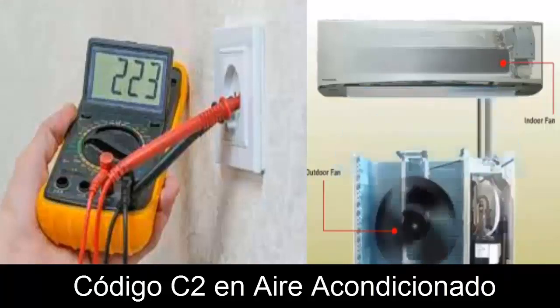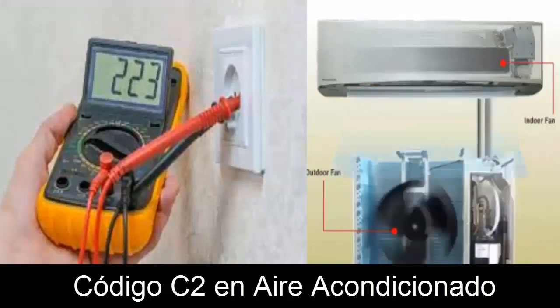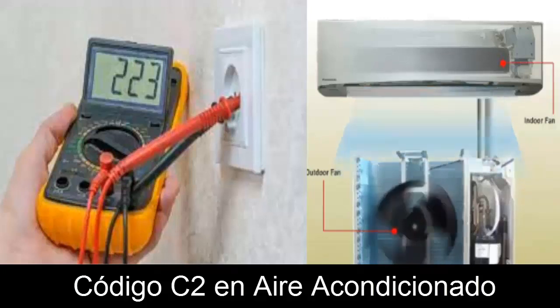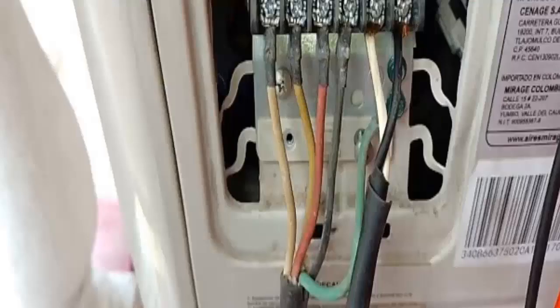C. Check the voltage supply from the external network. It should have an error margin of less than 10%. D. Check the connections of the unit's signal cable. They should be well connected.